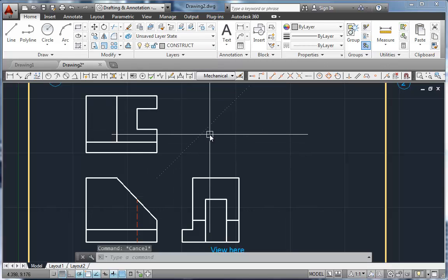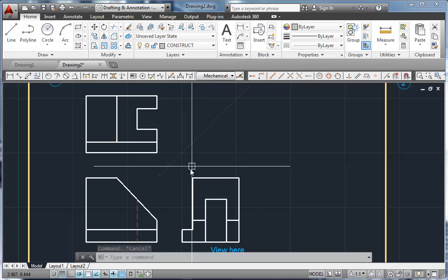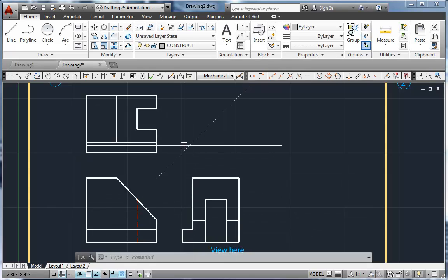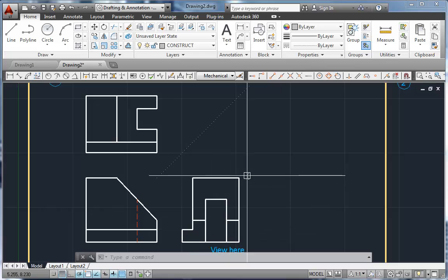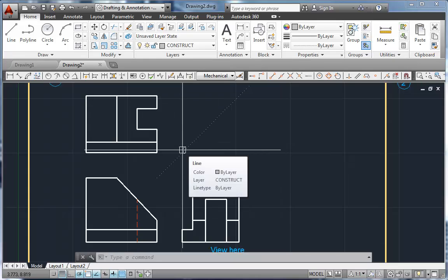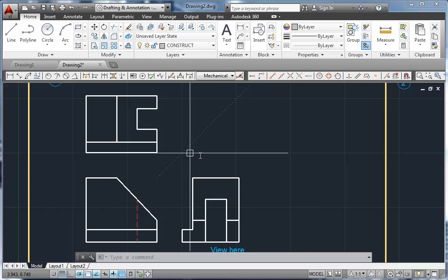But when we're grading your project, if you made an error in your miter line, it will change the width of this view. If we don't have the miter line, we're just going to count up all the mistakes and give you a deduction that'll be rather sizable. If we can see by seeing your miter line that it was a problem with the miter line, your penalty should be much less severe. So leave your miter lines in. You don't need to leave all the projection lines in, but do leave your miter lines.